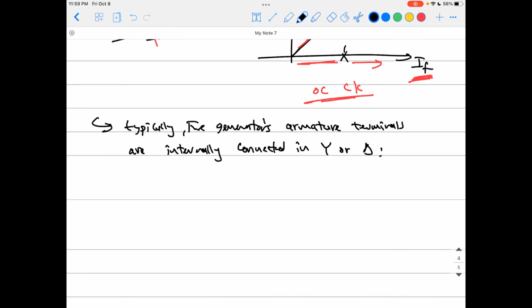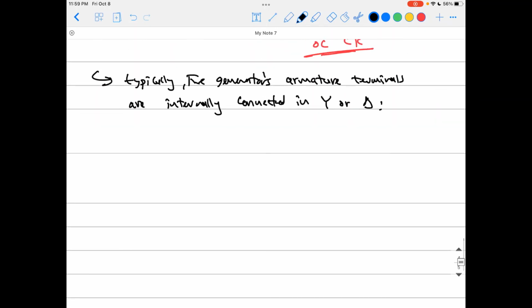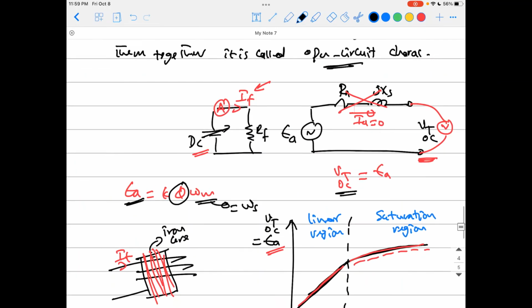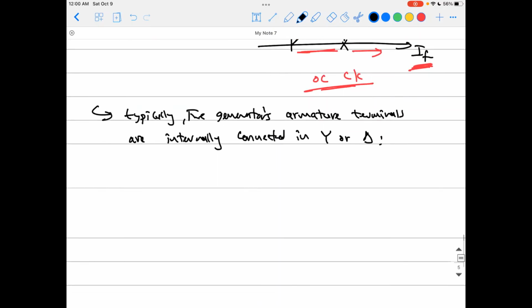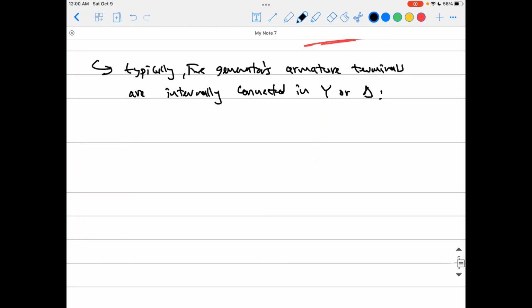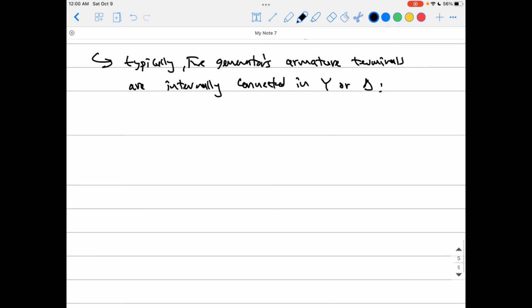Okay, so yeah, like I said, like I'm seeing here, we're trying to measure the voltage of this, and this is just per phase voltage, a single phase voltage. Okay, but sometimes you do not have the 6 terminals of the 3 phases, because each phase, each coil has 2 terminals, or you're just having all the terminals out.